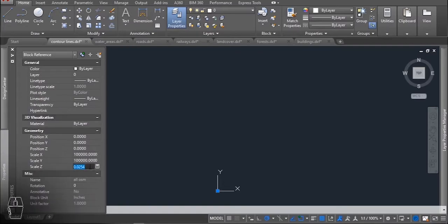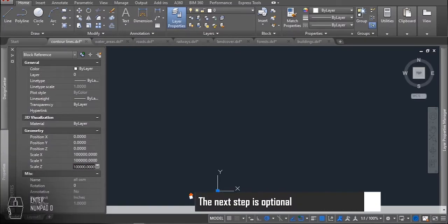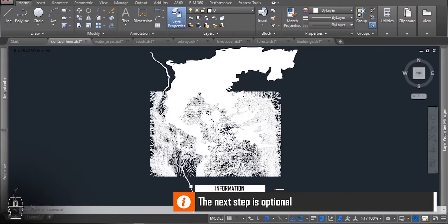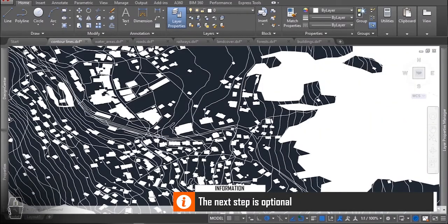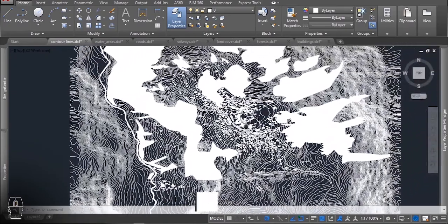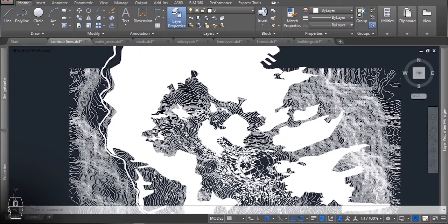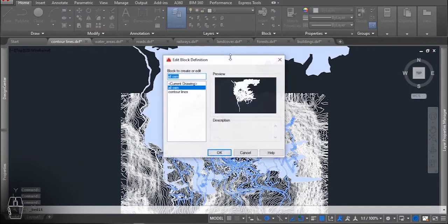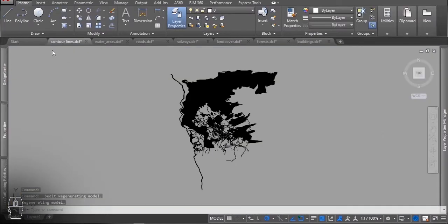The next step will be optional, in case you want to adjust the small defect in the drawings. You will find that the drawings are slightly stretched because of the wrong projection. Explanation of the problem: instead of using UTM projection, MyGeodata used geographic latitude longitude projection. You can fix this issue by following the next steps.